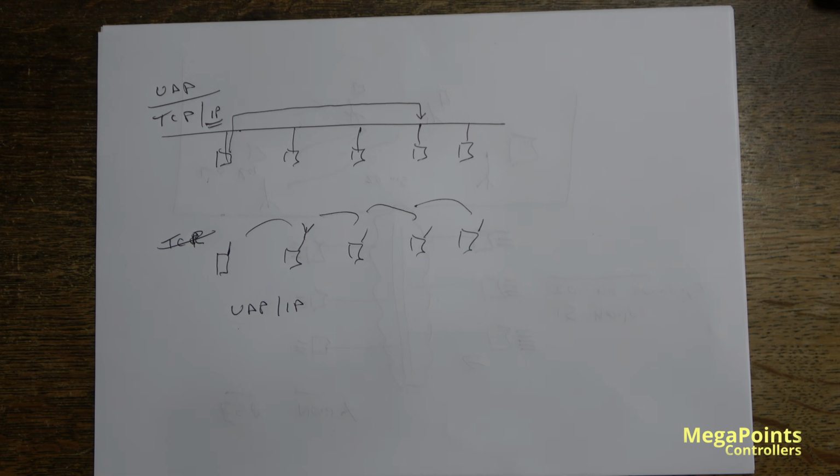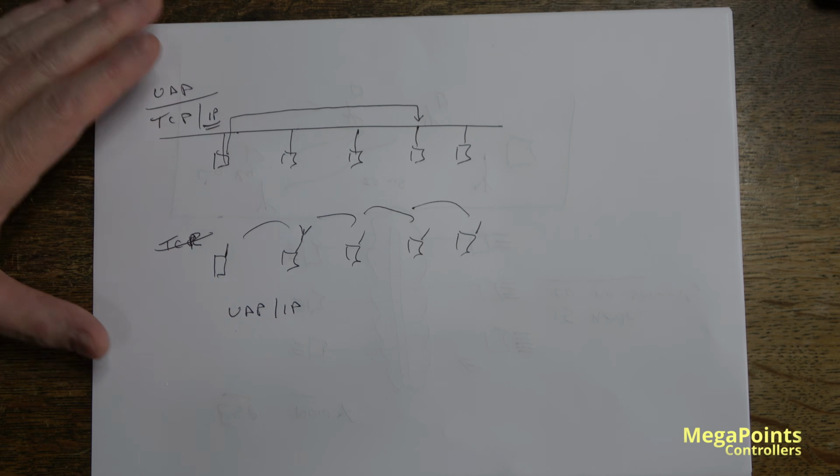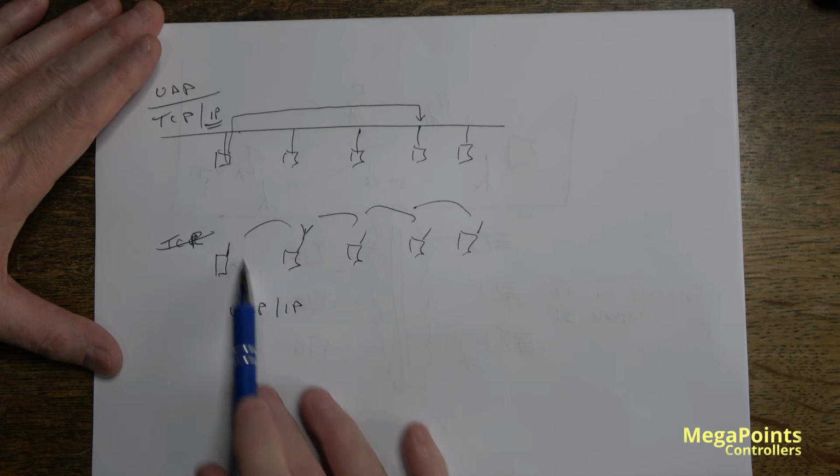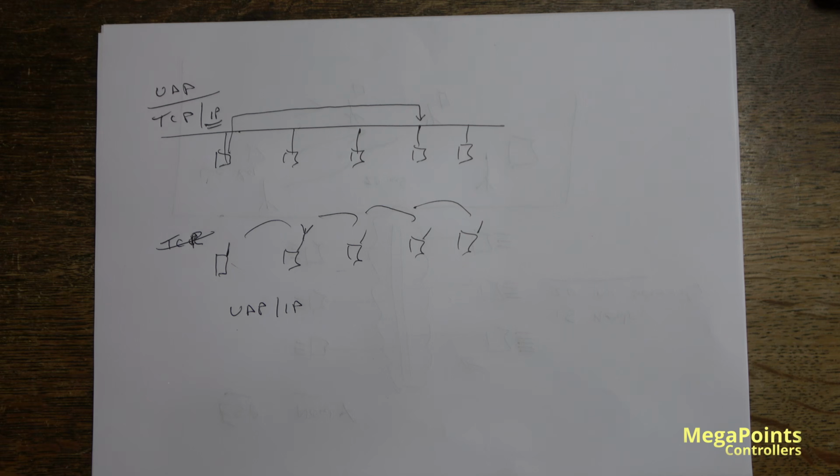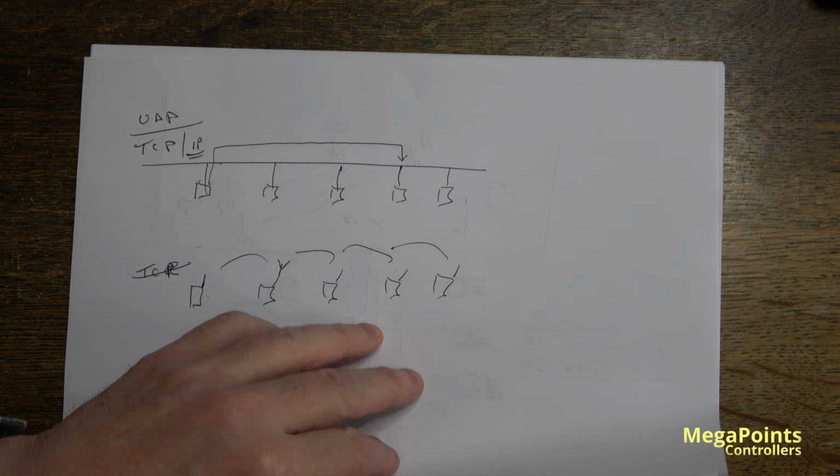But during testing, we determined that about 25% of all messages didn't get through. And that's unacceptable for a control system. If you're watching a movie, losing packets here and there or dropping frames is not an issue, you wouldn't notice. But when it comes to a control system where when you press a button, it has to respond, that would be clearly unacceptable and is just of no practical value. It's really flaky. So now we come on to MQTT.